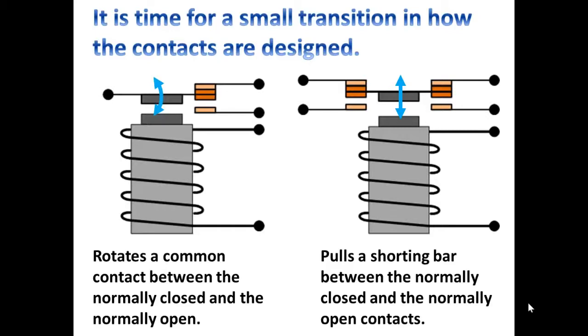What this gives you is 2 completely individual contacts for each position of the relay armature. That means that if there's an arc, the arc is divided between the 2 contacts. So that's an advantage. It reduces the possibility of the contacts welding together because of excessive current.